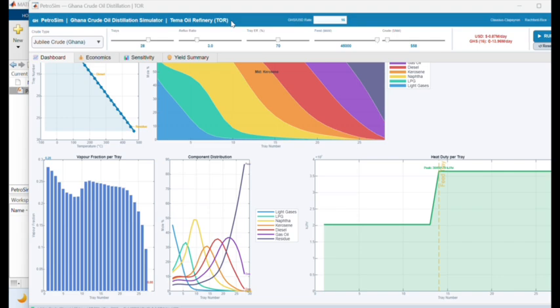So the first graph you had at the top left side, this is the temperature profile, and this is basically telling you the temperature at which each tray is at. Every component in the crude has where it separates. For petrol, you can expect petrol and other light gases at around -125, and the residue at temperatures above 500. Okay, so this graph is simply telling you what temperatures you expect at what trays.